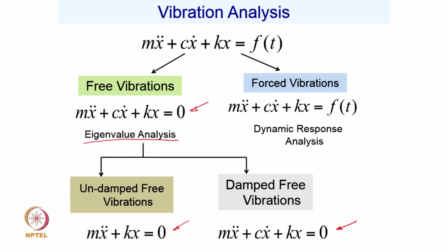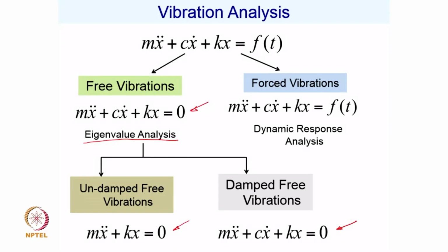Now, you would think that since all our mechanical systems do have forcing function or excitation inherent, and without that, 90+% of your mechanical systems make no sense, they do always have inherent forcing function, because all of them do have rotating elements, and then there will be always unbalanced excitation force. So, the question is, why do we really need a free vibration analysis or eigenvalue analysis?